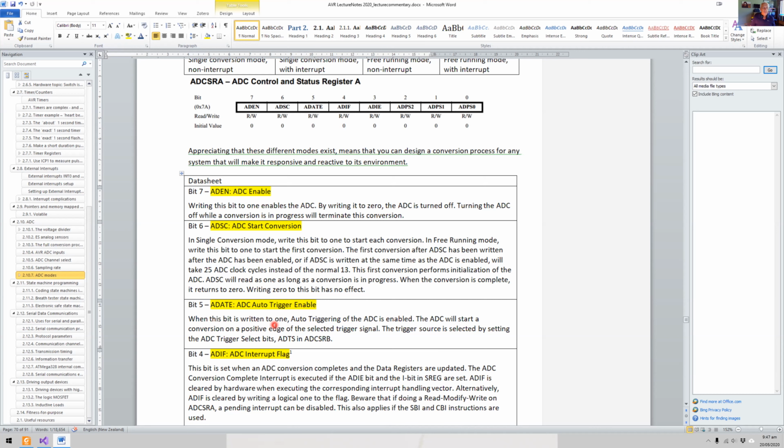We've got different features in the microcontroller that allow us to do things like set up a timer to do an analog to digital conversion. And indeed, there are 3 tutorials, I think, on ADCs, and the last one of those shows how a timer is used to trigger an analog to digital conversion. So this is, again, how we make an ADC do it.